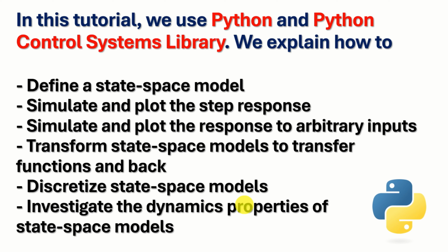We explain how to, number one, define a state space model, simulate and plot the step response of the state space model, simulate and plot the response to arbitrary inputs of a state space model, transform state space models to transfer functions and back, discretize state space models, investigate the dynamics properties of state space models and stability.